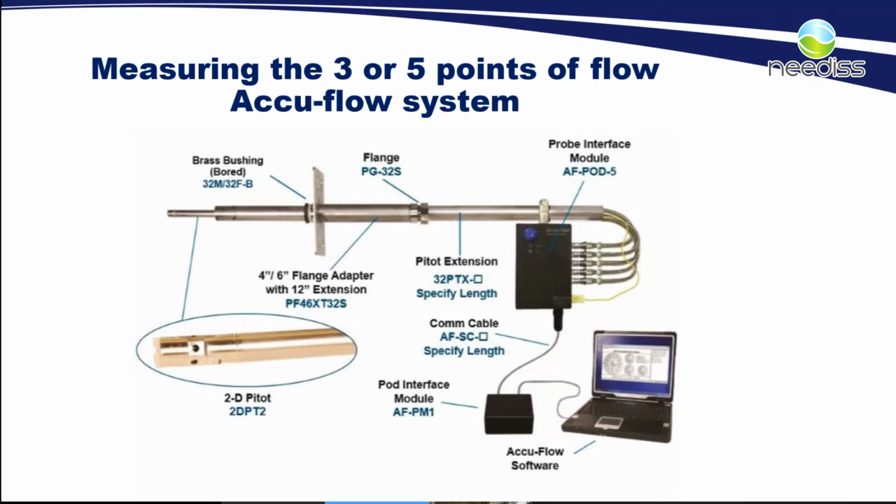Another reason is emission limit accuracy. If you have a facility that has what we call here in the United States a Title V permit, and within that operating permit it states exactly how much of a particular emission you can release into the atmosphere every year, you want that measurement to be as accurate as possible, because there are substantially large fines for exceeding your Title V emission limits as specified in your operating permit.